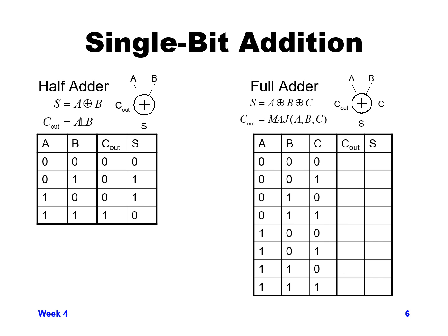Bit 0 would potentially be able to use just a half adder, but bit 1 would have to look at A and B coming in as well as the carry from the previous bit coming in. And so now we need to look at 3 inputs, A, B, and C, C being our carry, and we still have the same 2 outputs, C out and the sum.